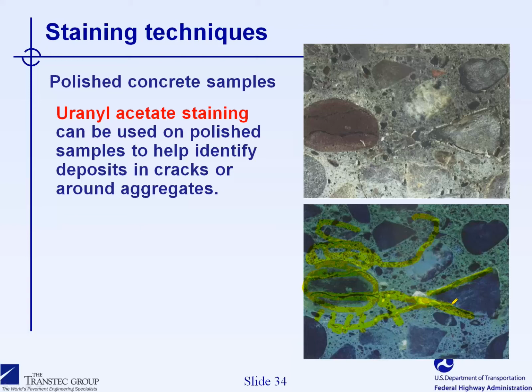Okay, the next question. How does fly ash or slag mitigate ASR? This topic was discussed during the webinar last week. Basically, to make a long story short, the supplementary cementing materials such as fly ash, slag, and silica fume contribute at reducing the pH, if you like, of the pore solution within the concrete.